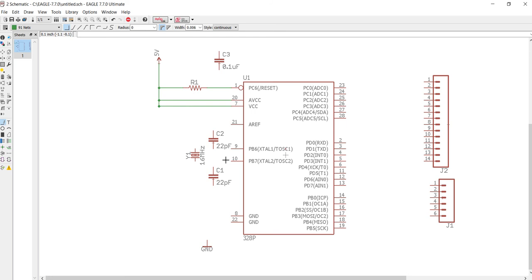And let's go back to our wire and continue to do some routing. So coming off the first crystal line, we connect it to there, and then terminate it at our crystal. And we left this one a little bit too low. We'll just move that up. And you see it automatically created the junction there. So let's add it in here. And if we want to verify if it actually touched, we can come in here and move this around. You see how it pulls it around? We know for sure that it's actually connected.